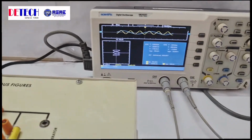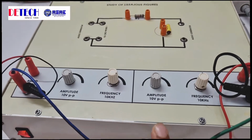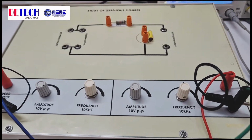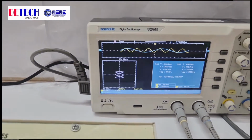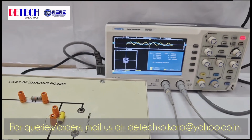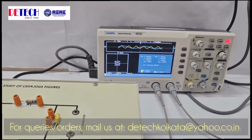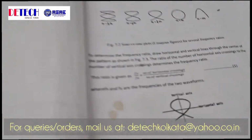So likewise, we can change the values of the two frequencies, and according to the relationship between the two different frequency signals, we will get patterns on the screen. And from the horizontal and the vertical axis, we can find out the frequencies of two waveforms just from the Lissajous pattern, and that calculation is given in the manual over here.